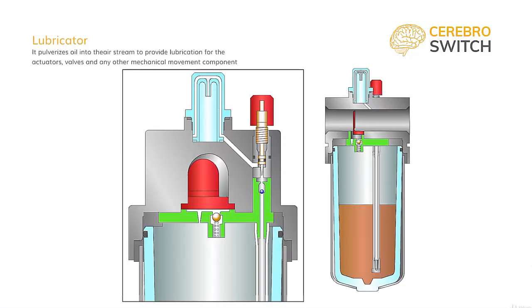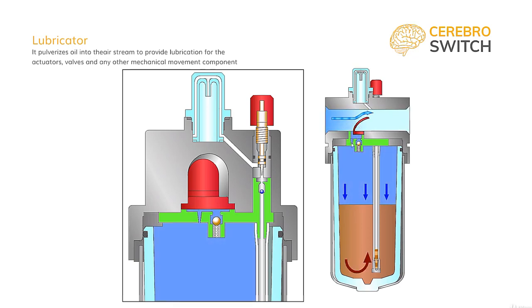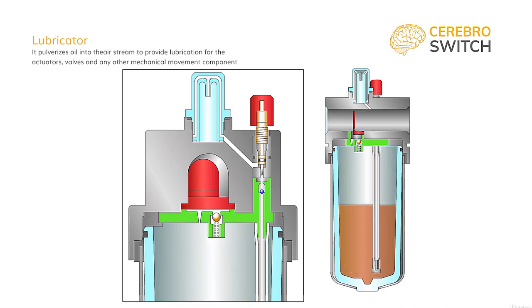Let's take a look at how the pneumatic lubricator works. The assembly comprises a body which has a straight air path but with a rubber flap. Most of the air flows directly over the bent flap, but in the process the flap gives the airflow some resistance. This resistance is small and it will direct the air into the oil bowl beneath.